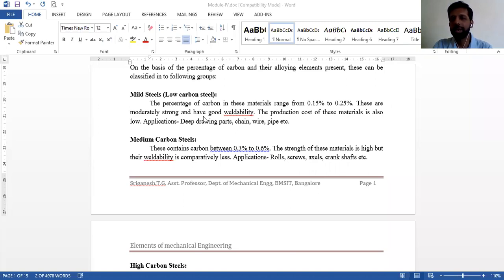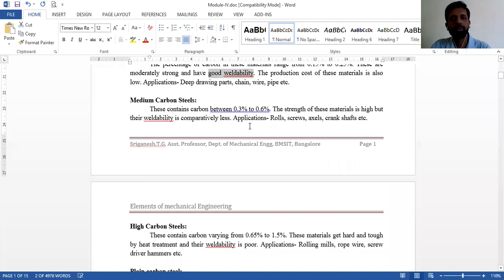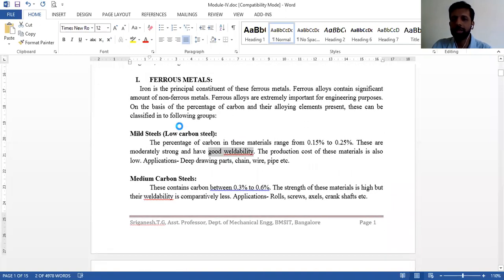As well as that, when it has been exposed to air, it will easily change its color, from the dark gray color of iron content to a brownish color, where the surface gets corroded because of the contents present in the atmosphere, so they will lose their iron content. Whatever iron is present will immediately get converted into ferrous oxide or ferric oxide. That is why they change their color. That is where it starts to degrade, that is, they start to get corroded. So they have very low corrosion resistance properties. That is how low carbon steel will behave.